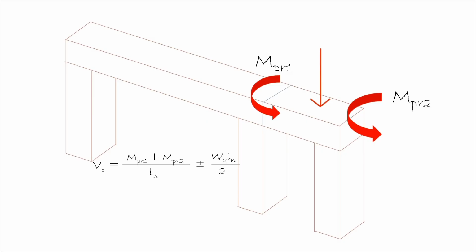So in our floor framing, we have two options here to remove the TC max failure. First, we can remove either Mpr1 or Mpr2, so the shear force will lessen. Option 1 is to remove the column here, so this beam will now act as a cantilever. Option 2 is to remove the other column, so this length Ln will increase, meaning increasing the span will reduce the shear force. For me, I shall remove this column to make the beam act as cantilever.